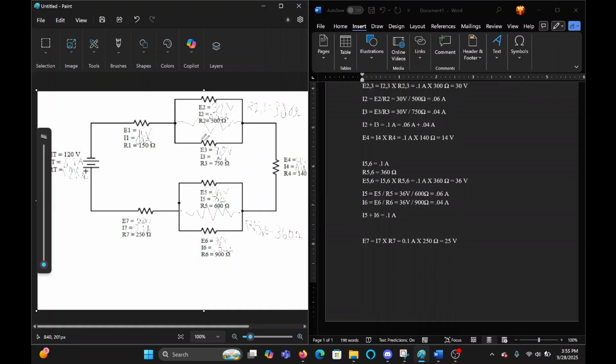When you look at parallel circuits inside a series, you should look at it as a series first. So we're going to calculate the total ohms, and then look at what the current is for the total system. Since it's a series circuit, the current should remain the same. So we can calculate the voltage going through the whole parallel section. Once you calculate the voltage, you only have one unknown. You have two knowns, so you can calculate that one unknown.